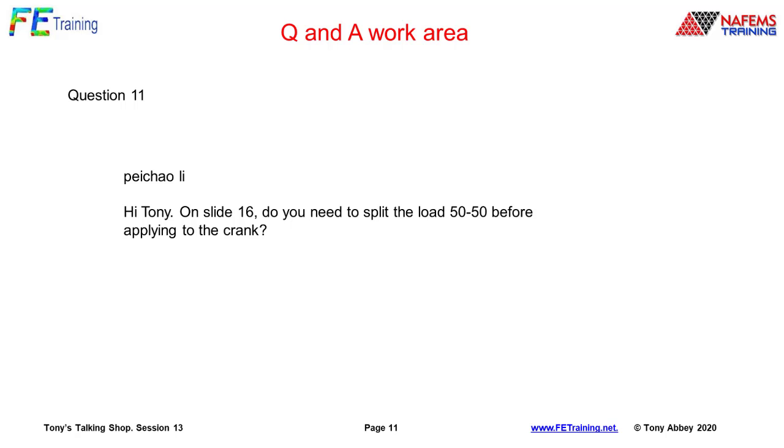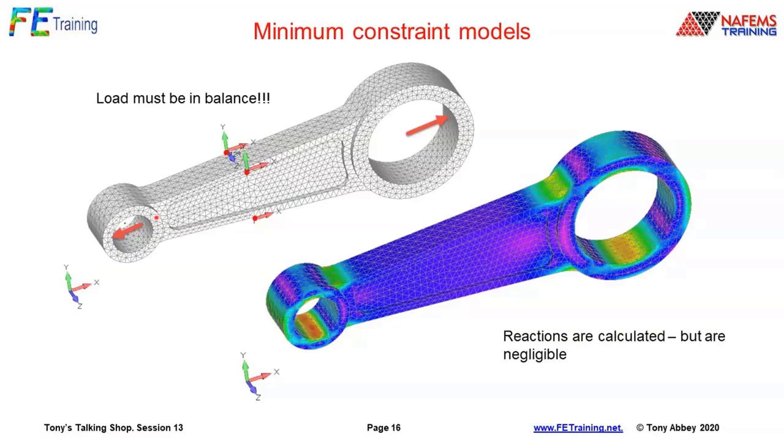I'm assuming that I've done a hand calculation to say this is without inertia. So in that particular case, let's say it's just the piston mass being flung out, let's say for the exhaust stroke. So we've just got the piston mass applying the load here, and let's say that was, I think it was like 5,000 pound, and then that's reacted by 5,000 pounds here.